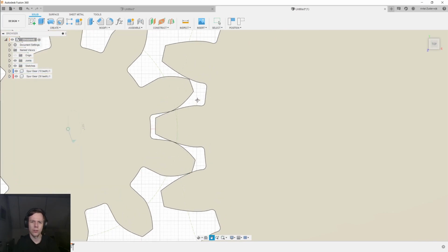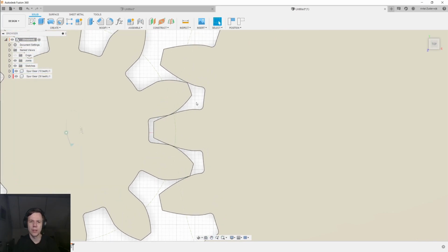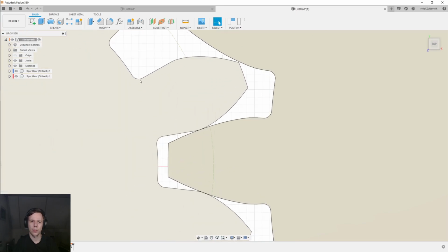And undercutting is, as I've shown you, a necessary part for making this meshing action work, but at the same time it also reduces the strength of the gear, because right where the stress is really maximum is also where the tooth actually becomes slightly thinner. So here we see a distance of about 4 millimeters, and yet if we look at the other gear, we see a distance of about 5.5 millimeters.